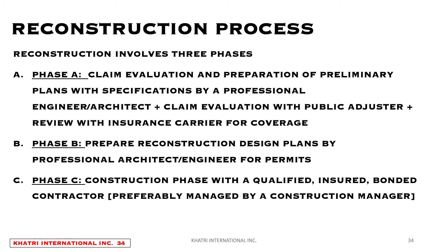And then before you go into phase C, make sure you don't skip phase B, which is to get a set of plans done and get permits. Because if you don't have permits, I already mentioned that earlier, you put yourself at risk. Phase C is the construction phase. Hire a qualified contractor, make sure they have insurance, make sure they're bonded, make sure they have an active license. If it's a big project, get a construction manager who can help you so that you can manage your project efficiently. And don't open up a new set of claims in your construction phase.